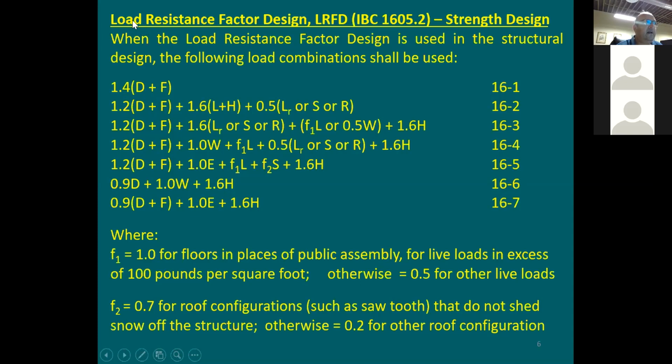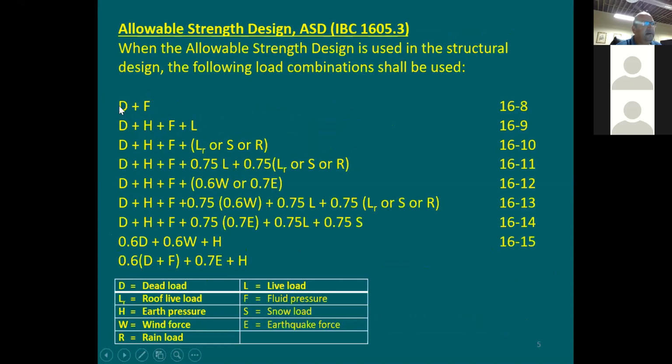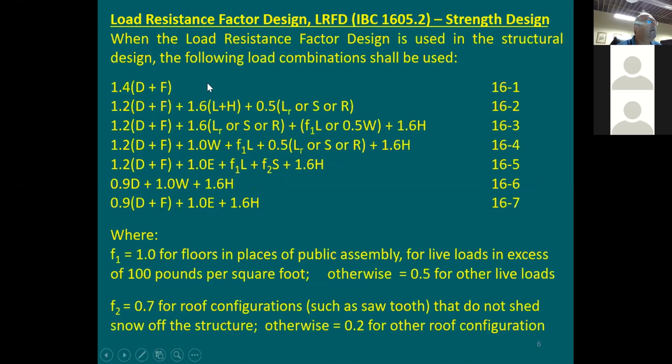As you see here in the LRFD, I have some load factors, and these load factors are more than 1. If I go back here to ASD, the load factor is going to be equal to 1, which means the demand is going to be equal to the service load. There is no change. Are you good? Any questions on the load factors? Yes? Nope, all good. You're good.